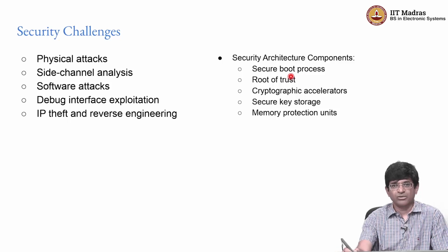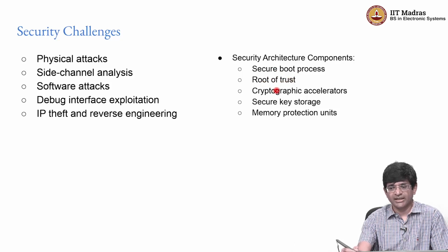A number of different things have been brought into SoC design to try and get around this, including what's called the secure boot process and something called the root of trust, which basically involves either trusted platform modules or some kind of individual blocks present inside chips, which make it very hard, if not impossible, to break into the system and reverse engineer the data being stored or communicated inside the system. Now again, this is mostly out of scope of what we are looking at in this course, but these are things to be aware of in terms of the challenges as far as SoC design is concerned.